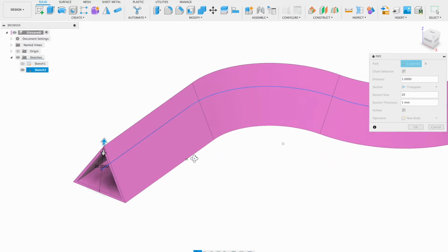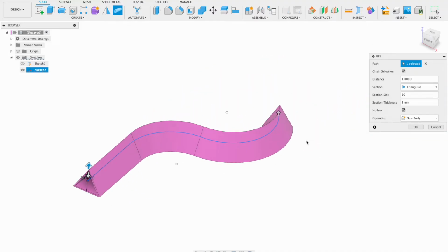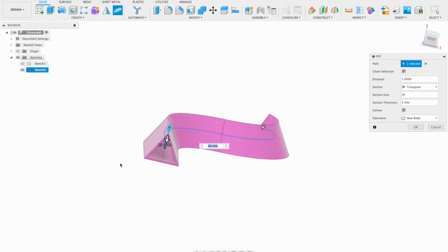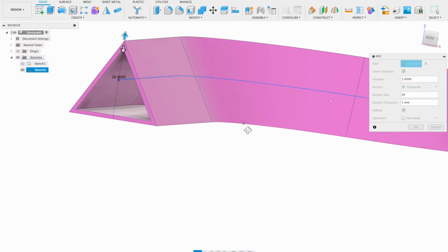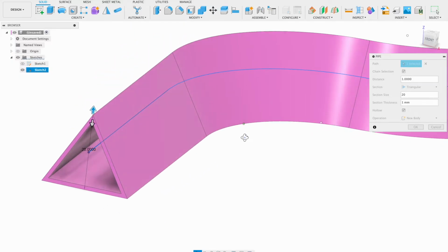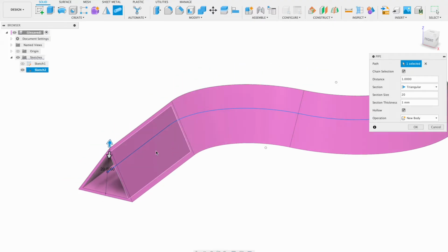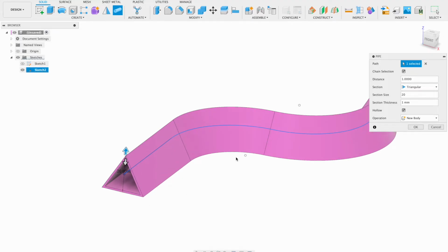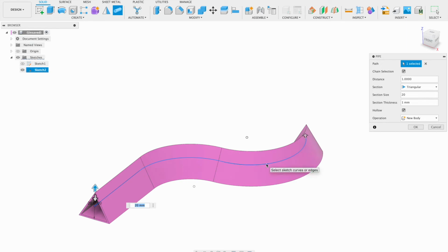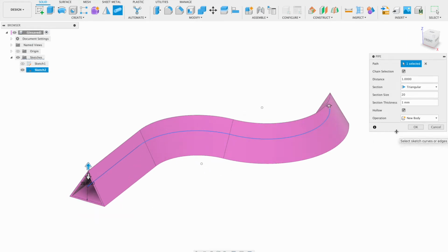In a triangle you have another option which the other two don't, where you select where the path is controlling. And what that means is once you click triangle, you have to be aware that it's taking the middle of that triangle as where the profile starts to sweep, let's say. Now that's important because if you want to have the triangle follow, let's say, the bottom edge, you have to create a sweep. It's not going to allow you to do that. Okay. So keep that in mind.